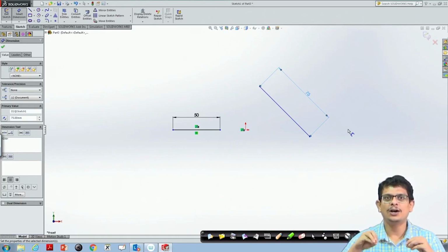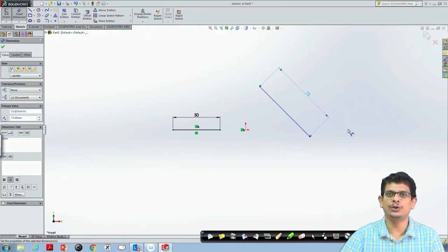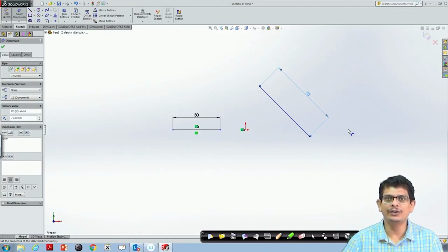My suggestion is, all the time for the drawing, use the same units of dimensions. If you begin with mm, everything goes with mm. Throughout the sketch that you are going to do, use only mm. Why I am suggesting this is because we are at part drawing level, we construct an object with certain units, maybe mm for this. For the next part, if we construct it in centimeters and we are not careful enough, we may not be in a position to make these objects and there will be a problem. So, all the time go with one system of units like mm.